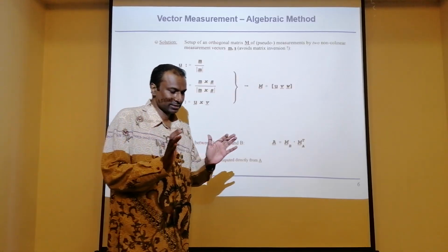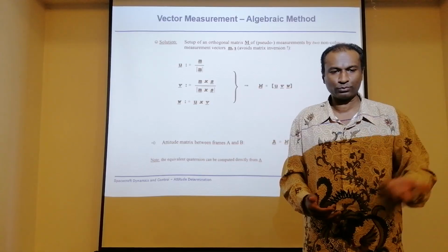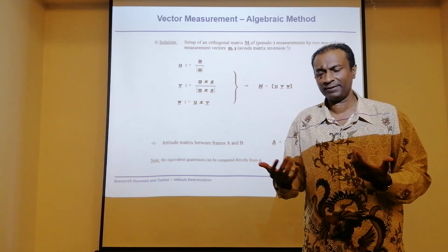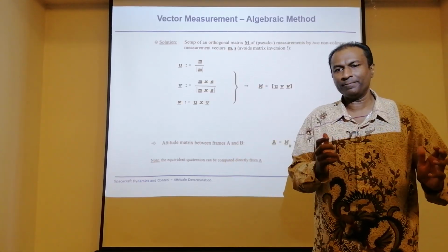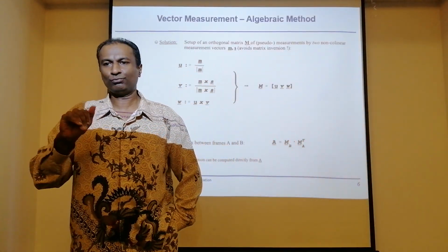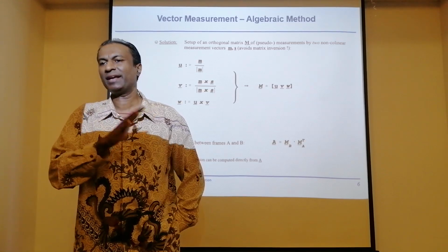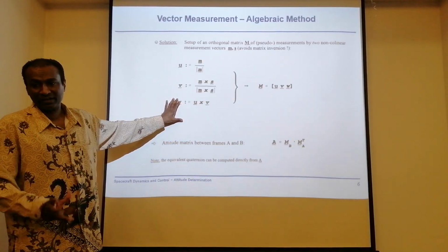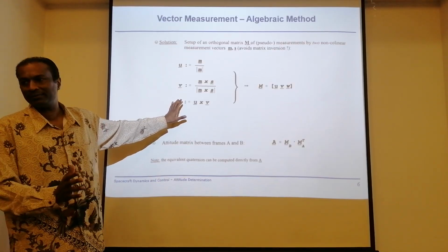So when you have a measurement with X, Y, Z, let's say alpha 1, alpha 2, alpha 3, you take that and rotate it into frame A or B. In the exercise that we have done before, all these are given to you, and we just ask you to rotate from one frame to another frame, and vice versa. This is what is fundamentally happening, and that is the reason you end up rotating.